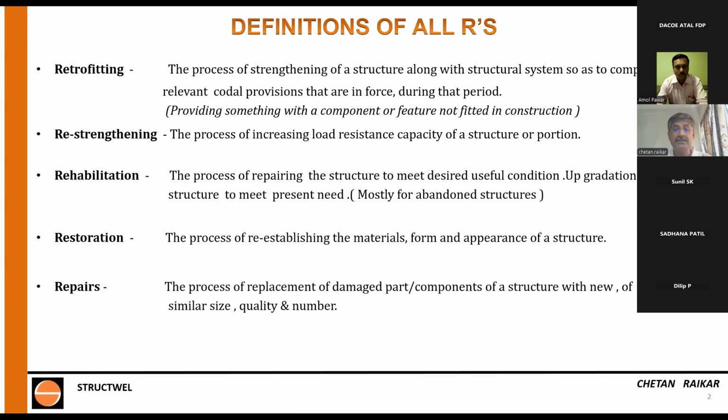And repairs, the process of replacement of damaged part components of a structure with new material of similar size, quality and number. Now, what's the difference between repairs and restoration? In restoration, you can upgrade it to the original condition also. This was the original condition. The structure has come down a bit in strength, in load carrying capacity, but this condition also is acceptable to me currently. So I am repairing a structure to this condition and restoring to the original condition. That's the difference.